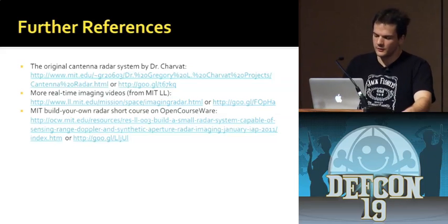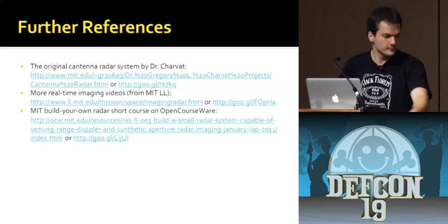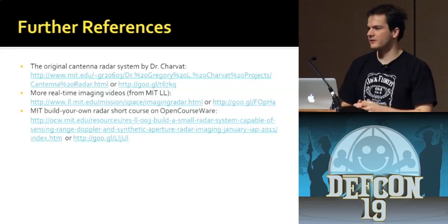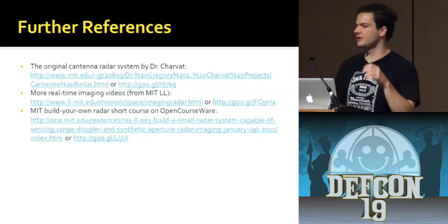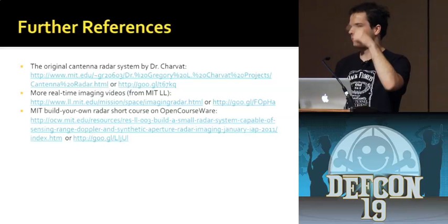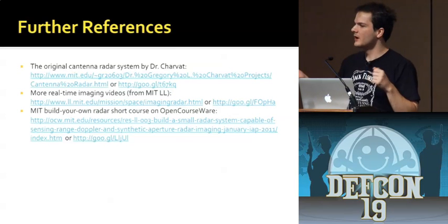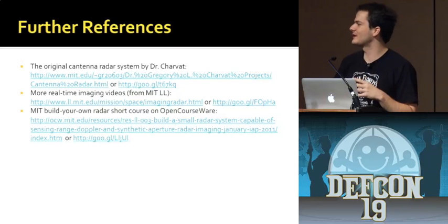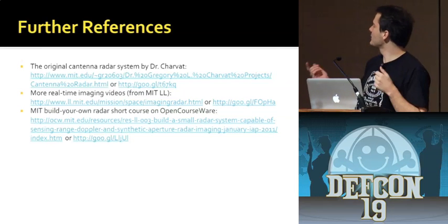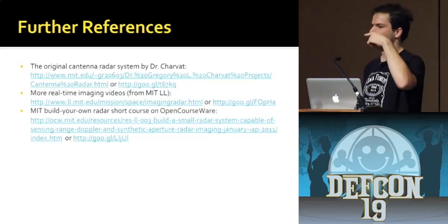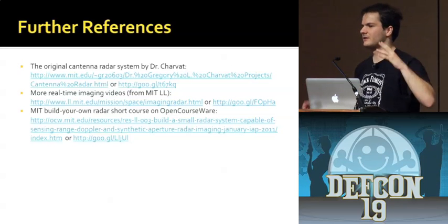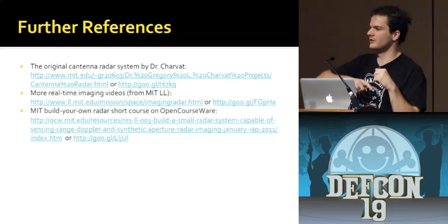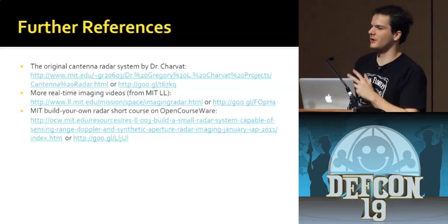Well, okay. What's the signal to noise with Wi-Fi? I guess it's pretty doable, because with the Wi-Fi signals, you actually see the bursts on the spectrum. I was shocked I didn't see that today. I was sure someone was going to be using a Wi-Fi device in here, but basically what happens is you get these little blips in the signal, and that chirp is affected. It's a pretty strong signal, and it's hard to filter out because it's not related to your signal at all. You're just basically sweeping right through it, and you pick up all that crap.